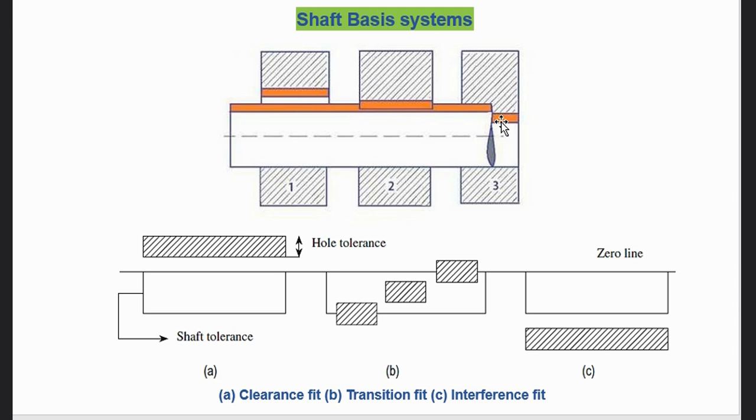I will make the holes by using a single drill bit, and I have a lathe machine, and by using the lathe machine I can manufacture any diameter, different sizes on a single lathe machine by using a single cutting tool. That is why I generally, or industry people generally, go with hole basis system. So this is what I mean by hole basis and shaft basis system.